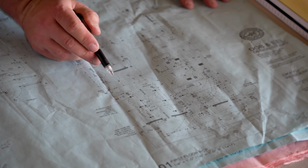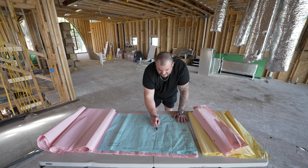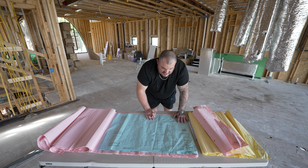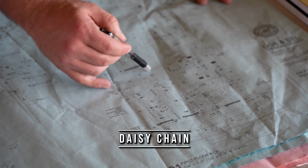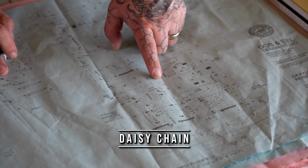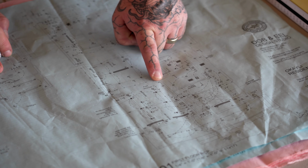And the good architects, they're gonna show you from the wall is 4 feet 4 to the center of this can. And then from the center of that can to this one is 6 feet. So again, you lay this out with your electrical contractor. These dotted lines are called a daisy chain. What that means is you can always trace that back to a switch.